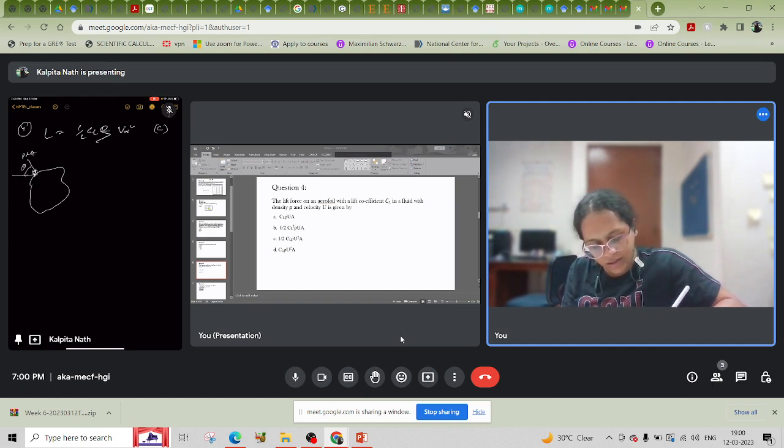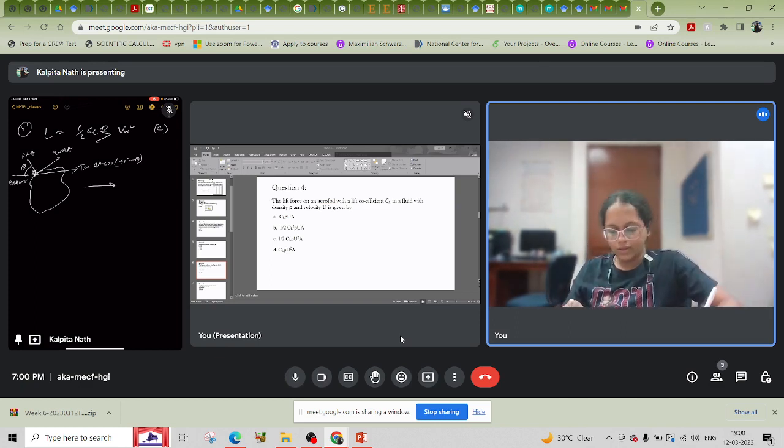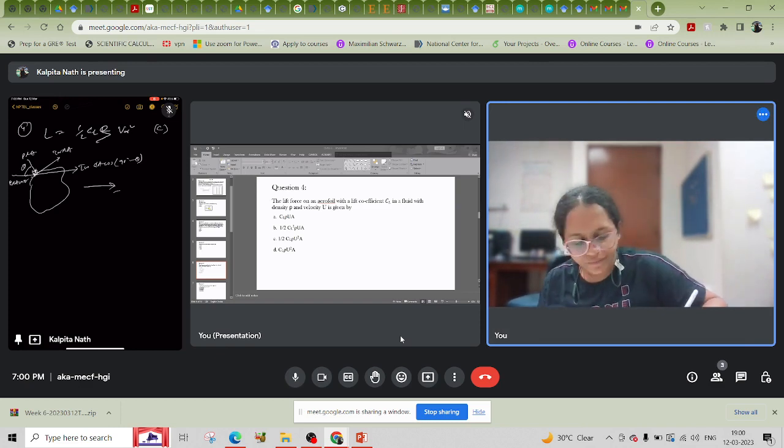This makes angle theta with the horizontal, and this is tau_w dA, this is p dA cos theta, and this is tau_w dA cos of 90 minus theta. This is the direction of force. Now p dA cos theta is the pressure applied in the direction of flow.